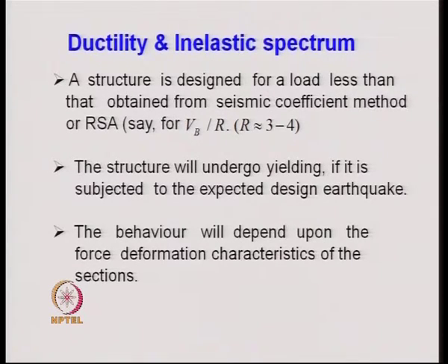We have to provide the load deformation behavior for each of the elements of the structures, that is the cross sections where we expect the plastic hinges to form. For those cross sections we provide load deformation characteristics or moment rotation characteristics from the designed cross section.